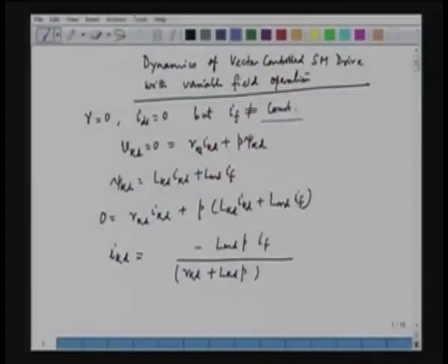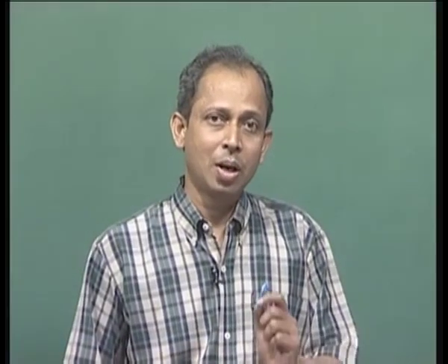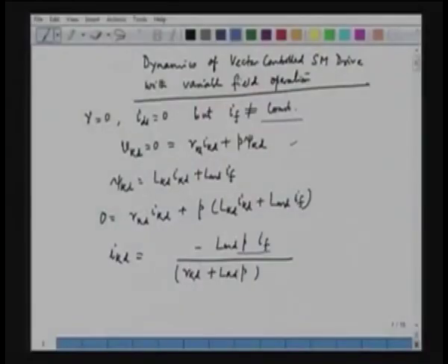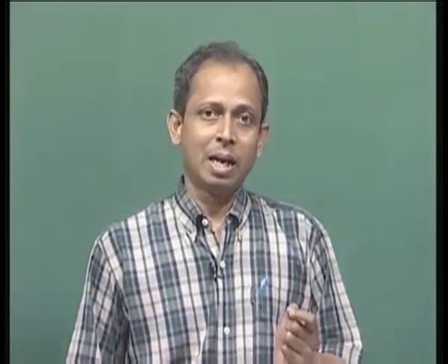We have the damper equation here, Vkd equal to 0, Rkd into Ikd plus P psi kd, and psi kd is the total flux linkage in the d axis damper winding, which is given as Lkd Ikd plus Lmd into If. When we substitute this in the previous voltage equation and simplify for Ikd, we get an Ikd, because If is not constant, and hence the derivative of the field current is non-zero.